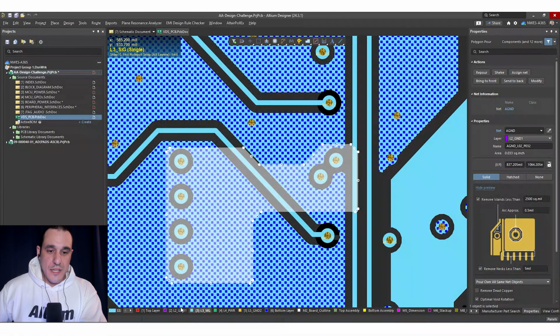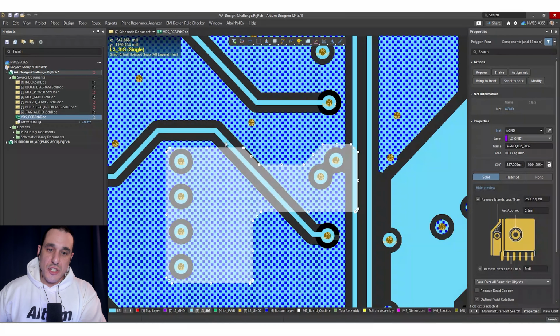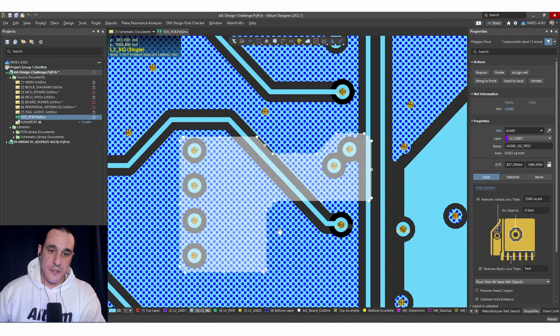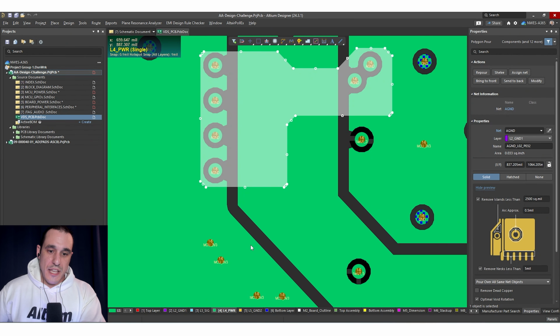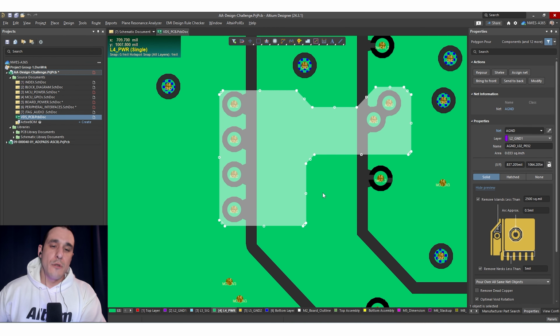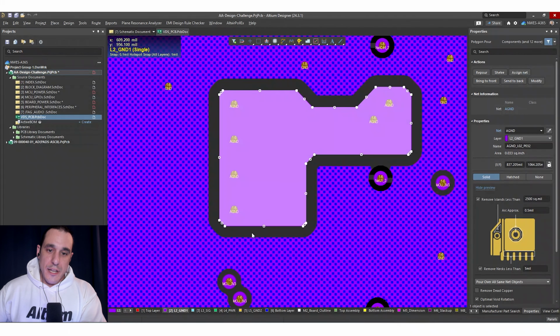If you are going to do this type of ground island right here, you want to make sure that you just don't do this with this signal, and instead just take this signal and route it around down over here. That way you're going to avoid routing over the splits in this ground, and you're going to minimize the number of splits that you route over here on power. So remember, it's already routing over these power splits. We would like to reduce any radiation from routing over those splits. The way you would do that is just eliminate these splits in this upper layer on L2. So that would be my recommendation here.